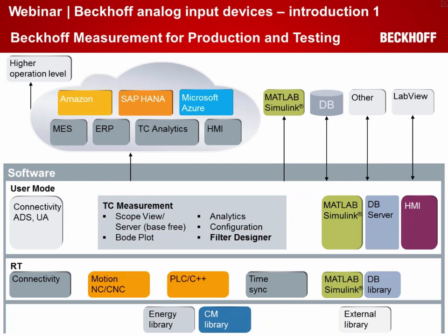So you can really run from a standard IPC with EtherCAT 50 microsecond cycle time with hard real time on a standard IPC. Time synchronization is a big issue in automated applications and in test stands and in laboratory, because our system and the devices can very easily be synchronized against an external clock.